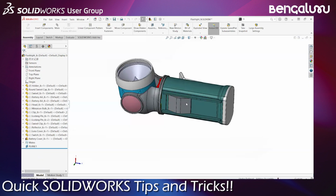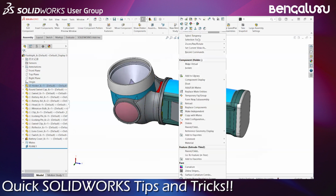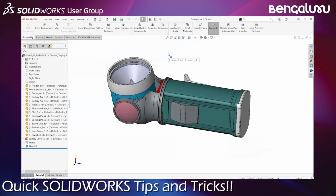Okay. So now when I want to see components within this assembly, I just want to hide this part and then take a look at the assemblies within. So the general tendency is actually to right click and then use this hide component command from here, right? That's one way to do it.